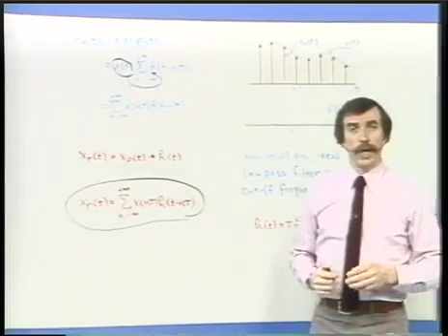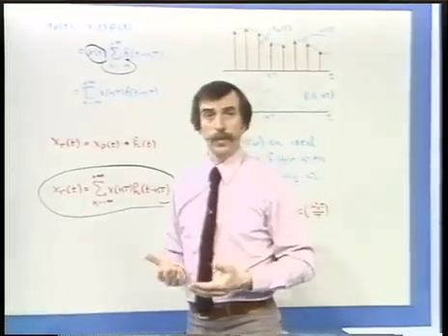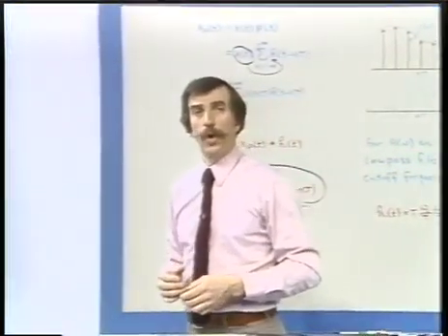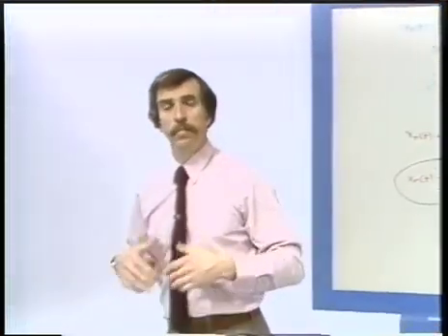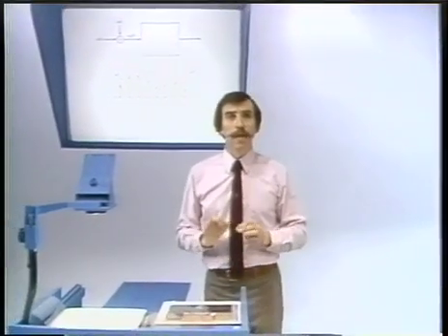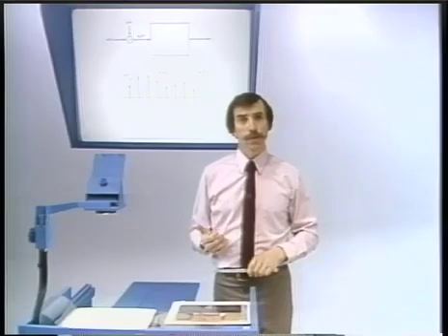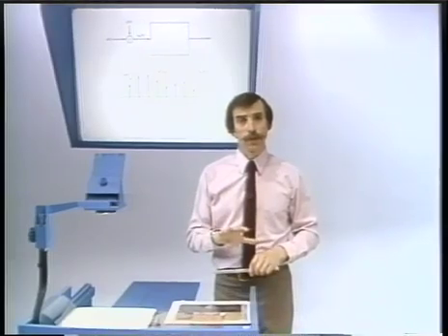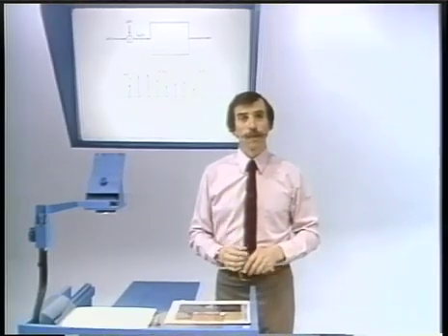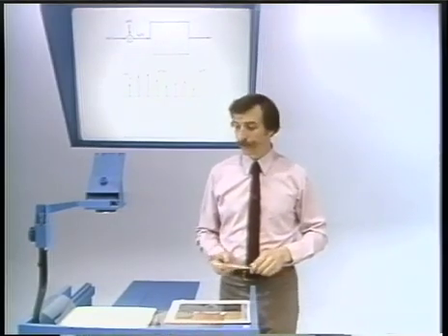Now, the kind of reconstruction that we've just talked about, and the ideal reconstruction, is often referred to as band-limited interpolation, because we're interpolating in between the samples by making the assumption that the signal is band-limited and using the impulse response for an ideal low-pass filter, which has a cutoff frequency consistent with the assumed bandwidth for the signal.